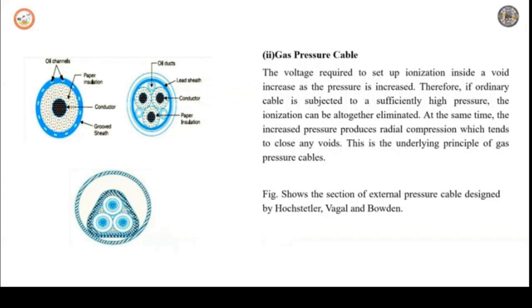The three core oil-filled cables use the shielded type construction. The oil channels are located in the spaces which are normally occupied by the filler material. The three oil channels are of perforated metal ribbon tubing. All the channels are at earth potential. You are seeing the diagram of how the construction is.